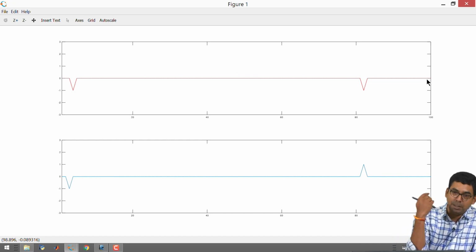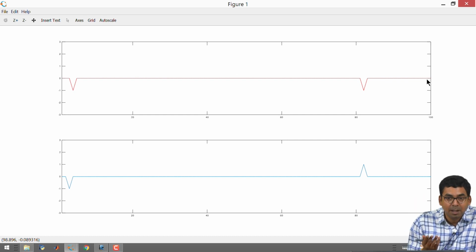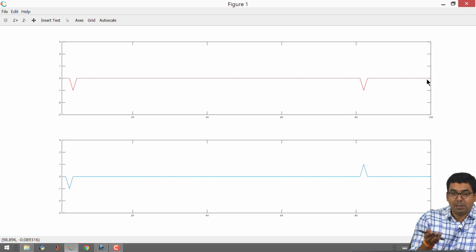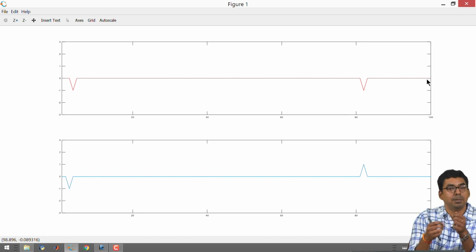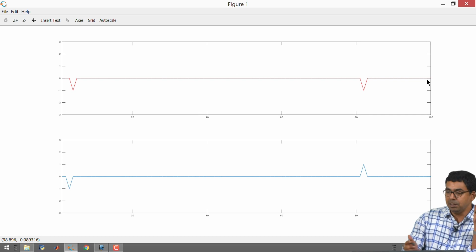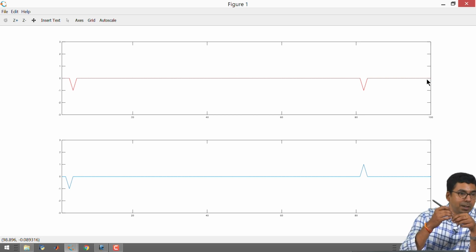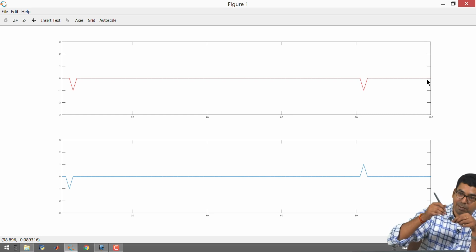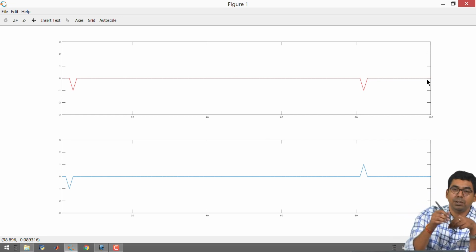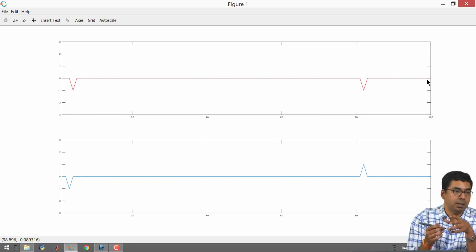If it is not flipped, then they know that it is corresponding to gamma is equal to 1, or the load resistance is going to be open circuit. So there is a breakage of the transmission line somewhere. We also know that the velocity in the transmission line is going to be equal to u. So you take the time at which you sent the pulse, all right, you will calculate the amount of time for you to receive the first echo, and then figure out how much distance it traveled two ways, and then figure out the location of the fault. So it gives you the location of the fault and the kind of fault that has occurred.